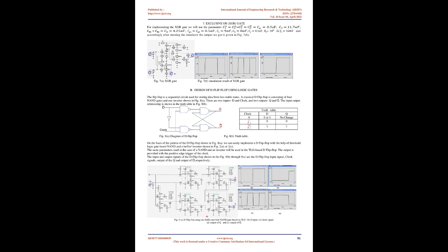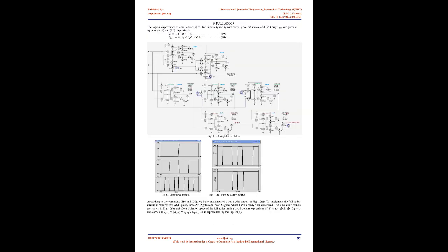This multiple input threshold logic gate can also be defined as a junction capacitor, C_J, circuit. Using the junction capacitor circuit we will be able to implement the linear threshold gate, LTG, represented by the signum function of g(x), expressed by equations 3 and 4: f(x) equals sgn(g(x)), and g(x) equals the sum of w_i x_i, for i equals 1 to n, minus θ, where x_i are the n Boolean inputs and w_i are the corresponding n integer weights.